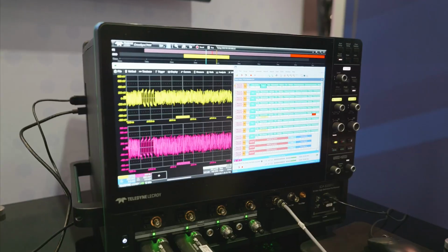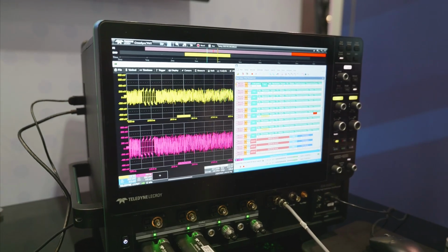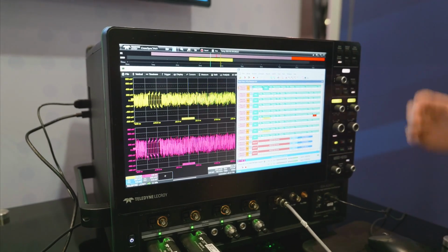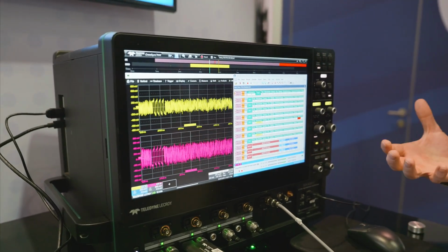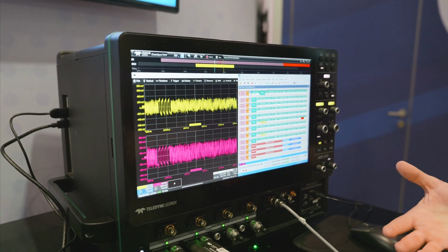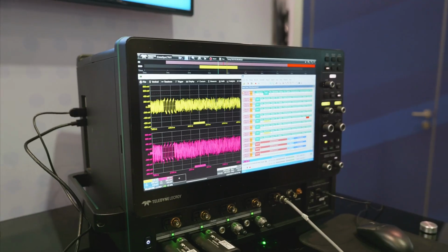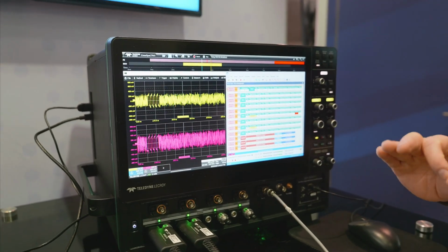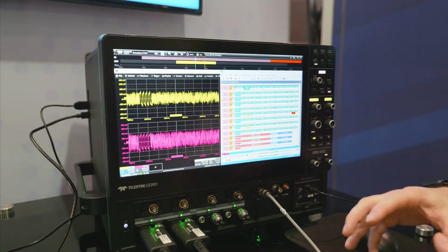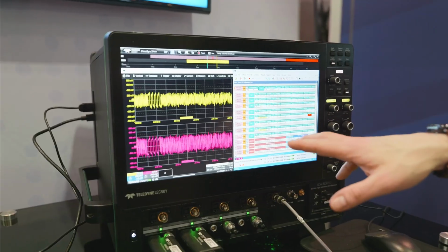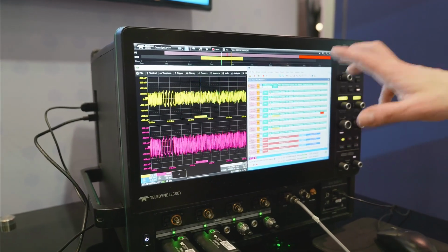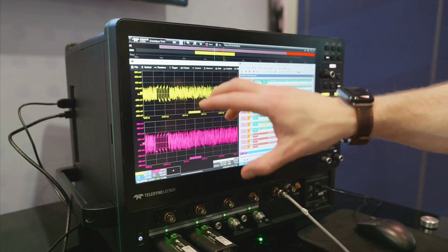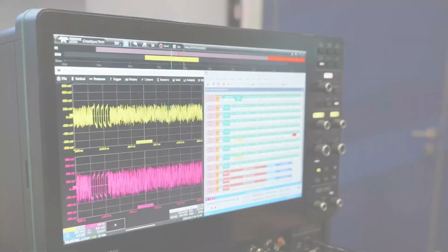And it's an answer to a question we've had many times, which is, I have two devices that I've used an instrument like your high bandwidth scope to prove are compliant to the PCI Express spec, but when I connect them together, they don't communicate properly. And the first question a lot of folks try to find the answer to is, is this a logical problem or an electrical problem? Cross-sync PHY allows us to look at both the protocol trace from the protocol analyzer and the electrical trace from the scope at the same time in a time-correlated way.